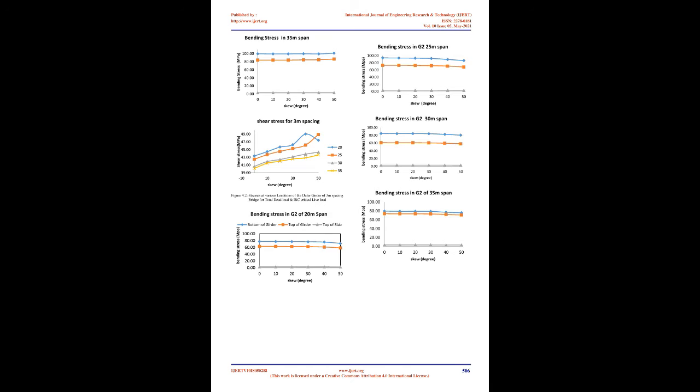From the results of various sensitivity studies on composite bridges, it is found that changing concrete deck slab thickness or bottom flange thickness has an insignificant effect on both moment and shear distribution, Senna 1999. Therefore, the concrete deck slab thickness is taken as 250 mm. It is also seen that the vertical web stiffeners have an insignificant effect on the load distribution, and so they are not considered in the analysis.